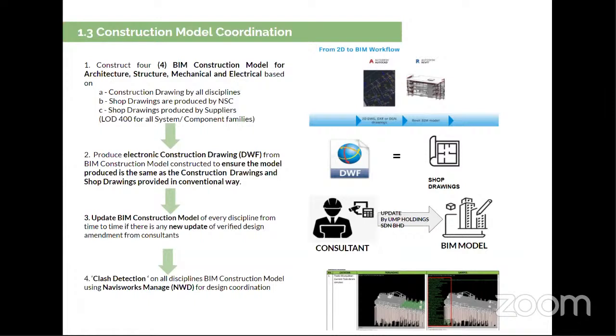So these are actually to tally back the conventional drawings, and then they will get feedback or any updates from the consultants, and then update the BIM construction model. So after all that, they will run the clash detections for all the disciplines using Navisworks Manage.